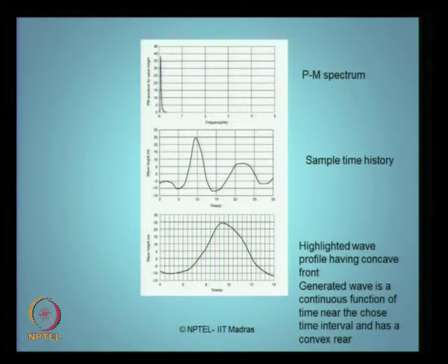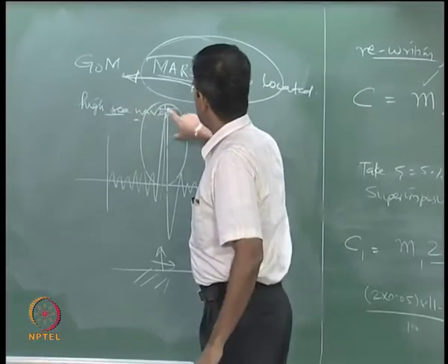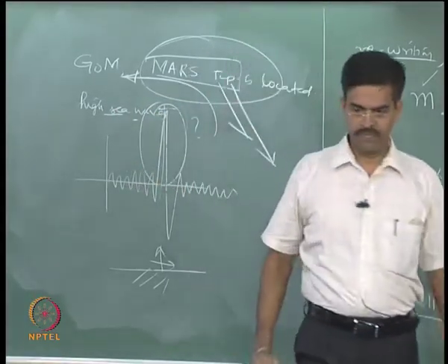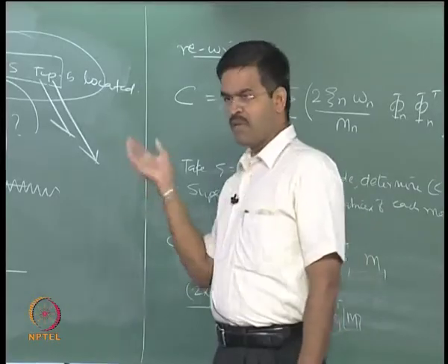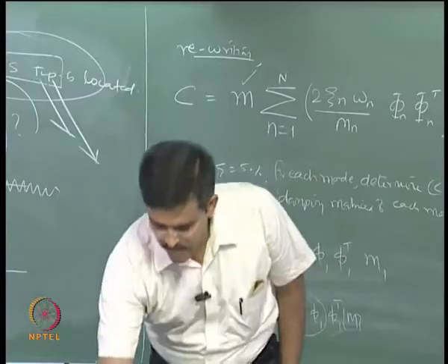by blowing up the specific time window, that it is having a concave front, is asymmetric in vertical and horizontal axis, and it is having a specific T naught peak which is many times larger than the successive peaks, what we call distinctly high waves. Okay. This has been completely mapped with the time history measured by Zhou and Kim in 2000, and they were experimental values, this is analytical value.